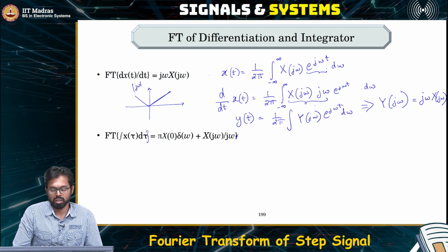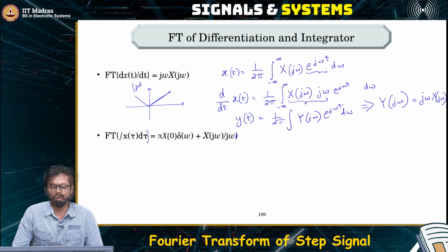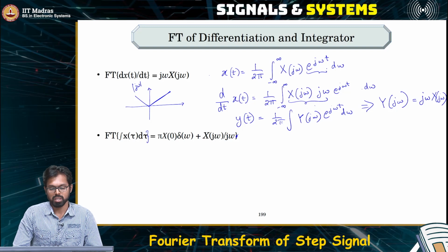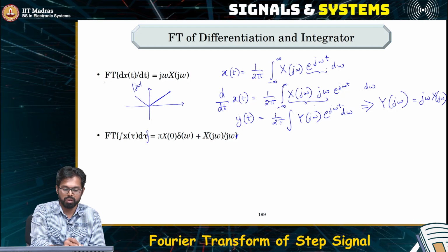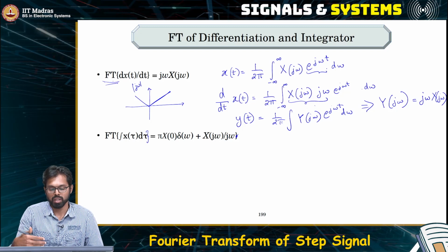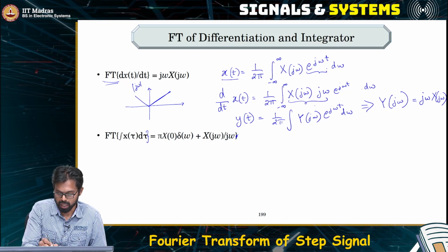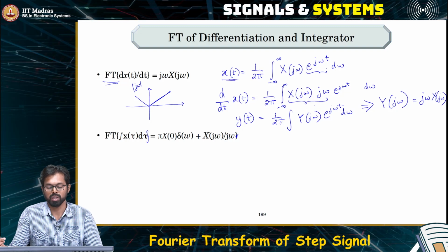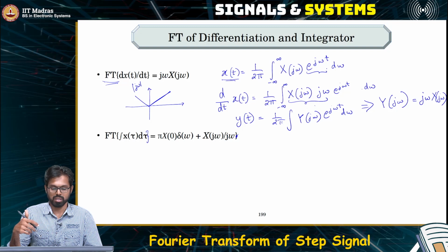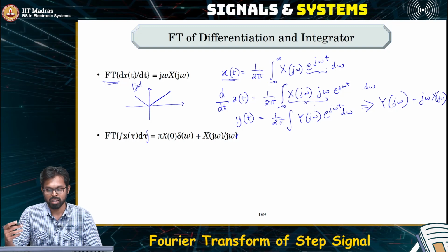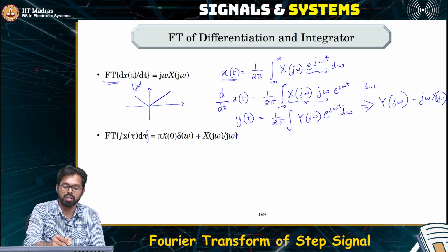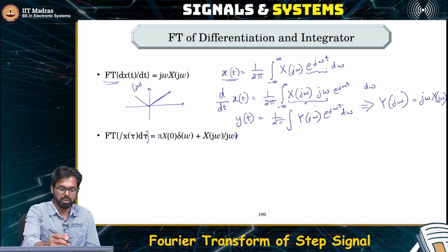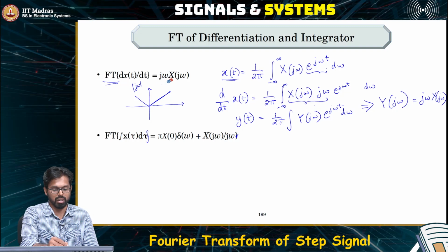This is also apparent from our eigenvalue eigenfunction understanding, right? The complex sinusoid or the phasor behaves exactly like an eigenfunction to the derivative operation. So when you compute the Fourier transform, what are you trying to do here? We are just expressing all these time domain signals as some scaled version of the complex phasors or the complex sinusoids, and anyway they are the eigenfunctions, which means all they'll do is get scaled by some amount, that's all, and that eigenvalue we know is j omega, and that's exactly what is happening here. Whatever is the input, it just gets scaled with the eigenvalue.